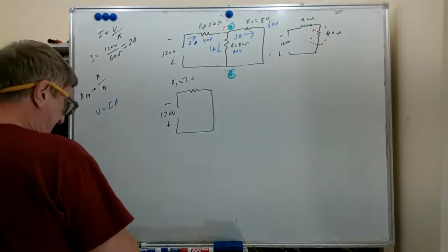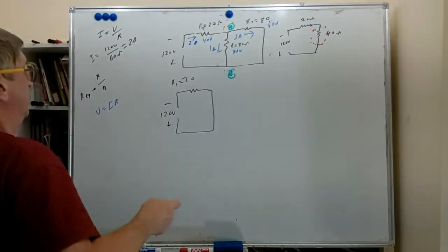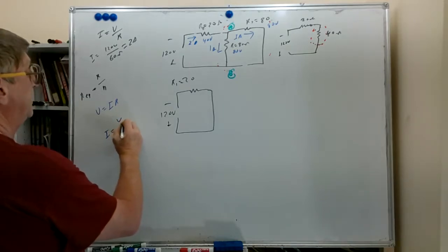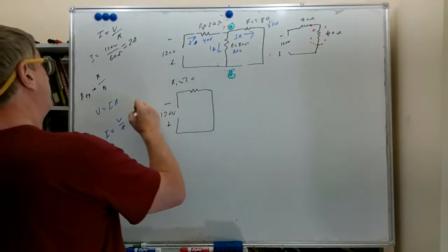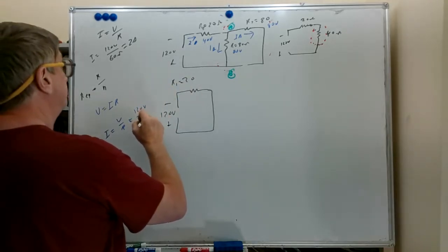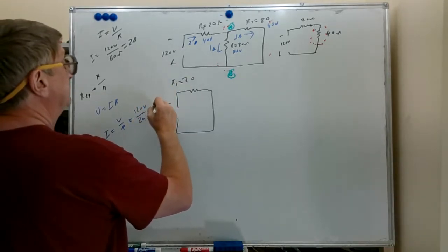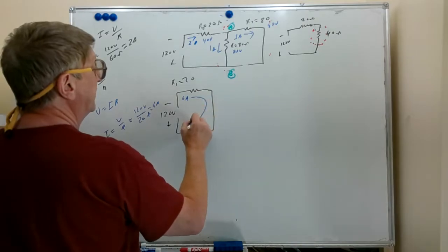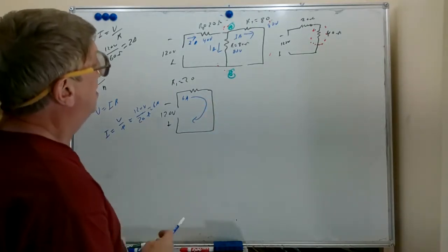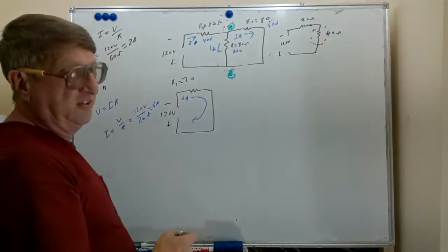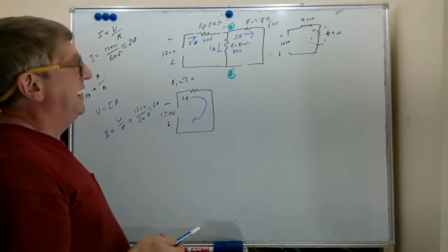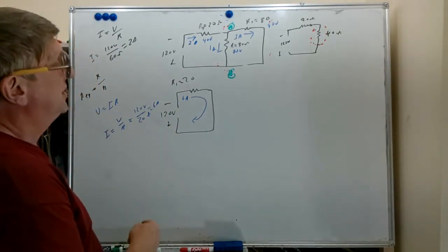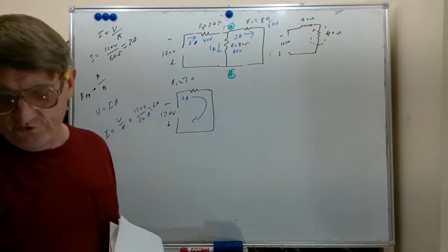So now what happens? Using I equals V divided by R, we have 120 volts divided by 20 ohms. Now we have 6 amps. So we now have 6 amps flowing around this circuit in this direction. But what you might notice, R1 had 2 amps, now it's got 6 amps. It's got 3 times as much current as it had before. That could be enough to cause R1 to overheat and destroy itself. So that's one of the potential problems that can happen with a short circuit.